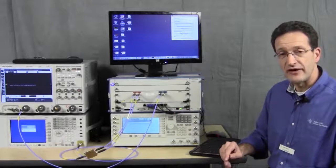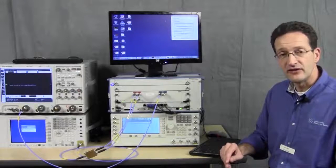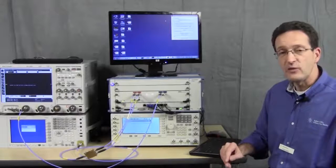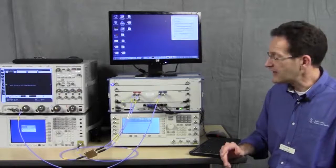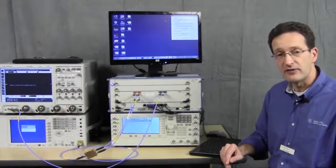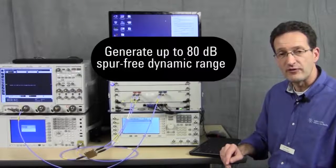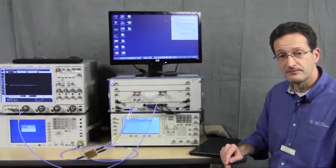With signal bandwidth getting wider and wider, it is important to have high fidelity signals at high bandwidth being generated. With the M8190 and up to 14-bit vertical resolution, up to 8 gigasamples per second sample rate, it can generate signals with up to 80 dB spur-free dynamic range. Now I'll show you some measurements using those products.